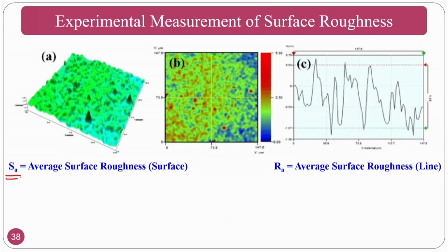This is the average surface roughness of a surface that is scanned, and you can also give the surface roughness value along a particular line, so that you can understand which area the surface roughness is more, which area surface roughness is less, but on an average what is the average surface roughness of that particular surface. Okay. This is about the digital value. It is a single value where you do not know the surface roughness profile.